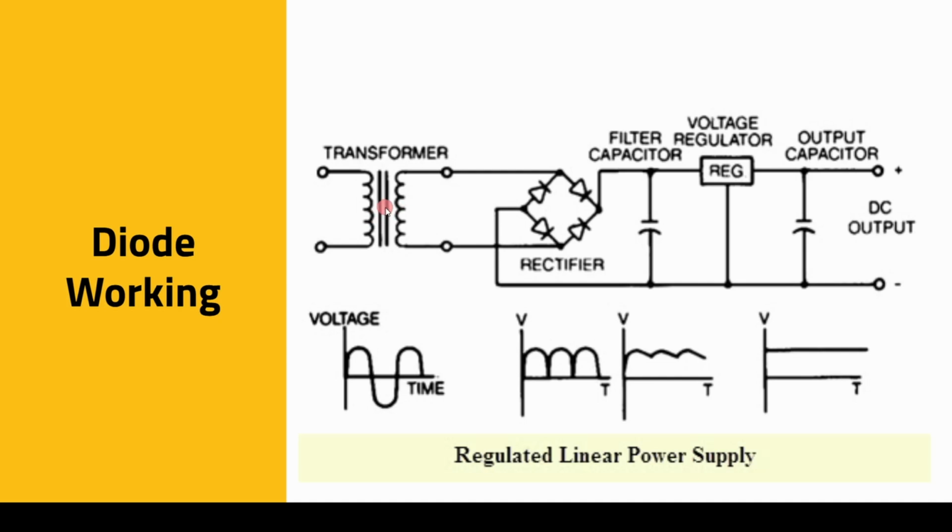They are connected physically, as part of the same transformer, but they are coupled through a magnetic process. So the output is safe to touch compared to the input, which is 230 volts. If you touch here, you'll get a shock, you'll die. But on the output side, if it's 12 volts, because it's not connected to the 230 volt supply in any direct fashion, it is safe to touch.